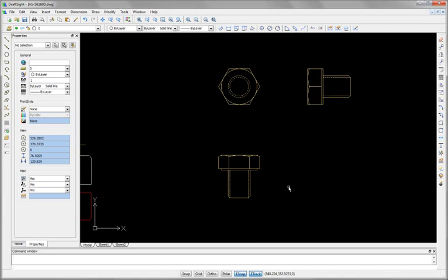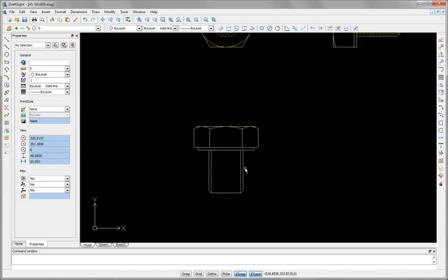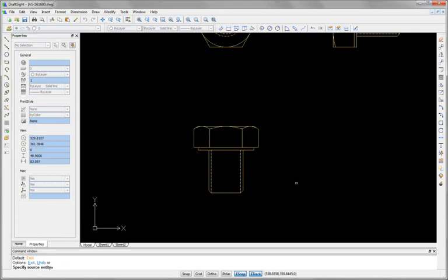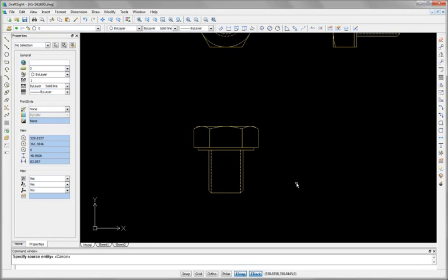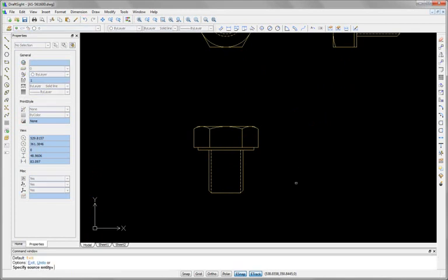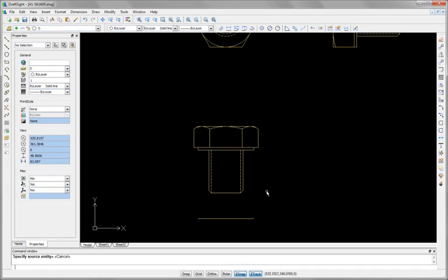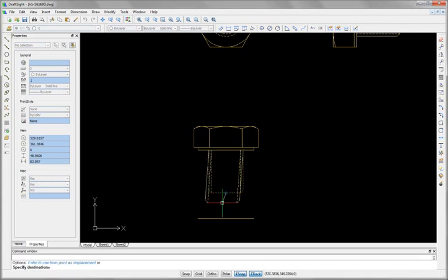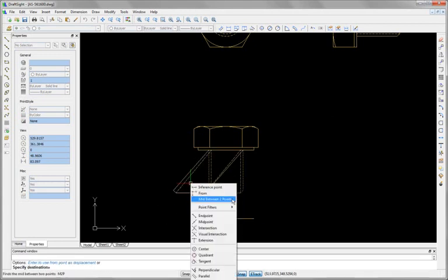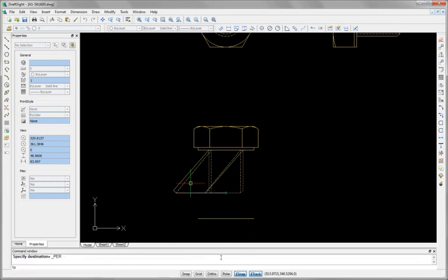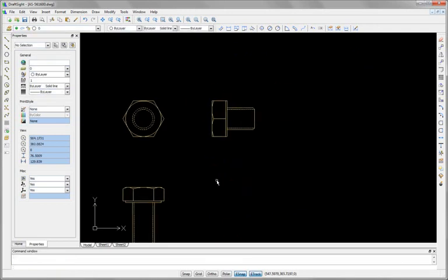The other thing that's unique about these components is their length. Our block uses a standard 10mm length, but we want to make sure that these are the 16mm fasteners that we're looking for. From the mouse gestures, it's very easy to quickly enter an offset value here. I'm going to offset that line, and we want to stretch this. Now I can grab the stretch tool from the side, and making sure that I'm perpendicular is easy with the context sensitive snaps. I'm going to choose perpendicular in this case, and we'll remove that extra line.